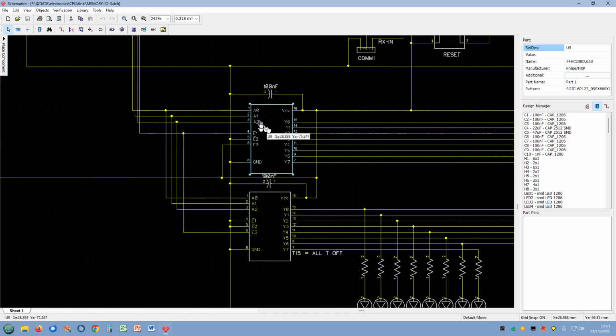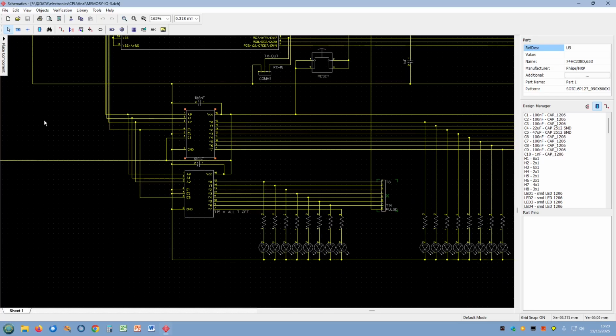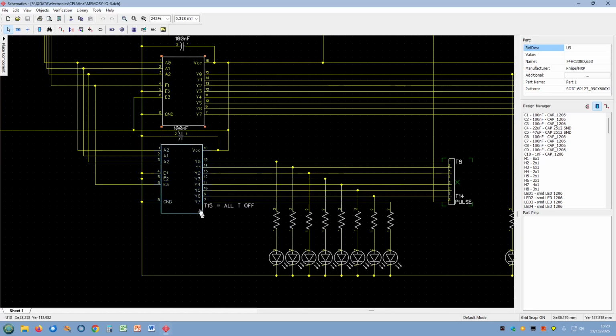So the only problem here is, because you've got 16 coming in, so you've got 16 going out, one of them is always going to be on. And there are states where we want the T signals to not be on at all, be nothing there. As T15 isn't used, I decided, well, that one, which gives you an LED there, well, if I switch all these signals on coming out, it will select T15, which doesn't actually go to the CPU. All it does is light that LED, which, believe it or not, is more useful than you think.